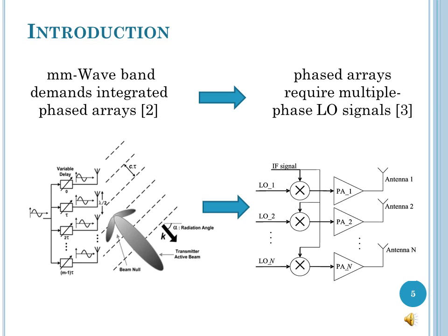The figure on the right shows the different phases of the local oscillator signal applied to the mixer as in a local LO phase shifting system. The experimental component associated with this research tests the feasibility and accuracy of a silicon germanium production technology based integrated phase shifted VCO for implementing a phased array system.